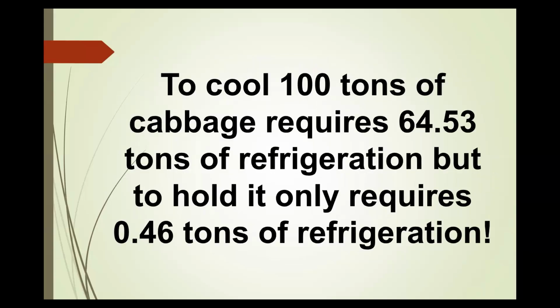To cool 100 tons of cabbage required 64.53 tons of refrigeration, but to hold it requires 0.46 tons of refrigeration.